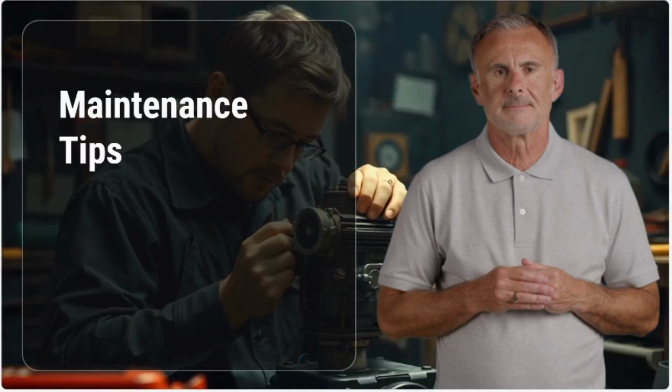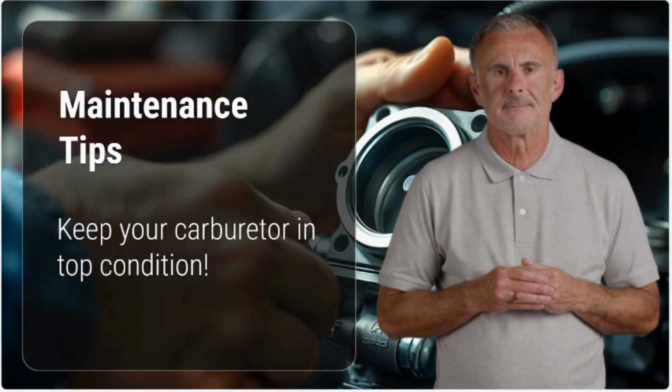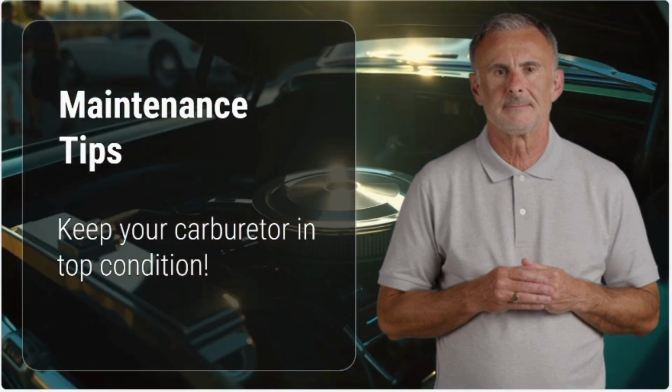Regular maintenance, such as using fuel stabilizers, cleaning jets, and ensuring the float bowl is free of debris or varnish, can significantly improve performance and extend the life of the carburetor.